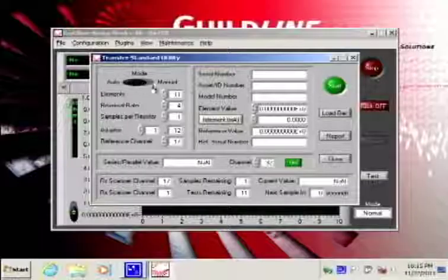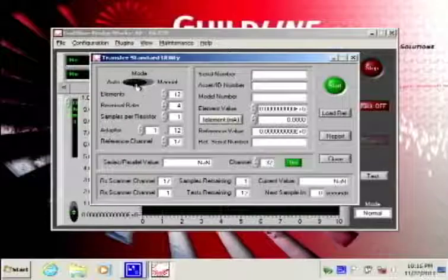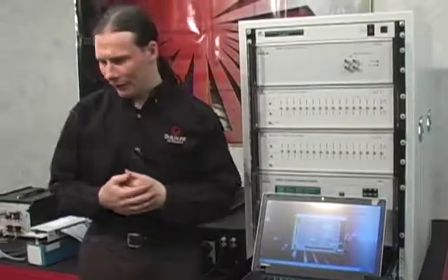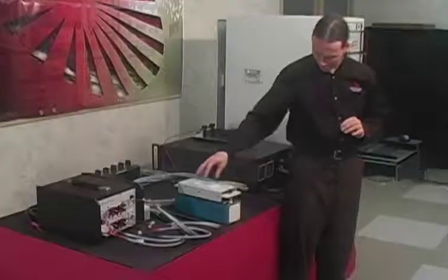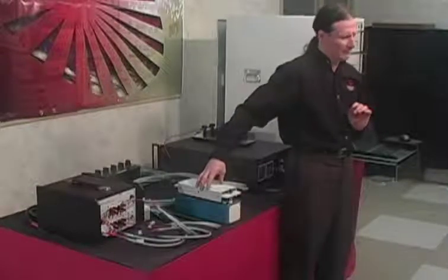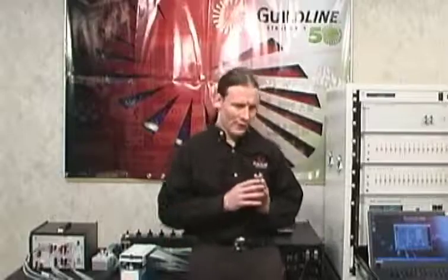So essentially, you see here you got your choice of number of elements is typically 12. And you can choose your reversal rate. I would pick something about 20 seconds for a 1 ohm. And how many samples you'd like to take per resistor. Bearing in mind that these resistors are about 1 ppm, which is actually quite a relaxed specification for the bridge.